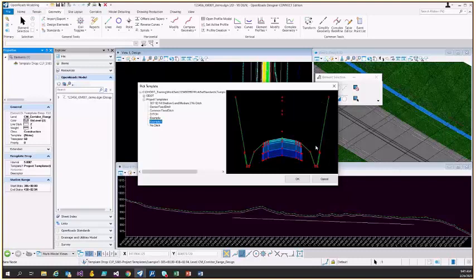this one. Just things like point controls, and if you have walls and you're doing some corridor clipping, it just starts to get messy. I mean, if you don't do anything more than this, then you could probably get away with leaving your fixed ditches, but my recommendation would be to use this as a starting point to get your ditch profile and then switch it back. That way downstream you don't run into more problems.